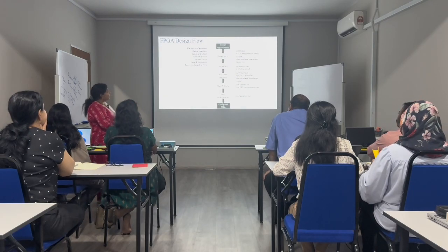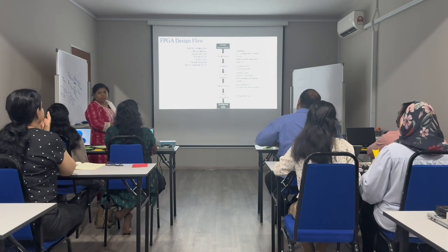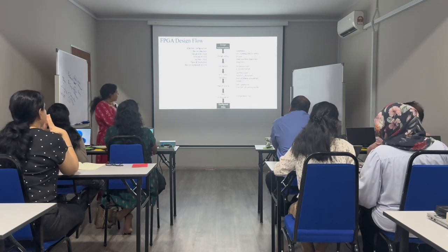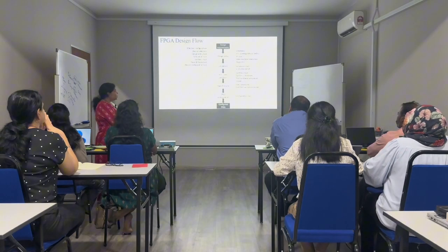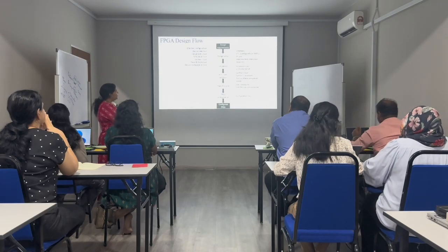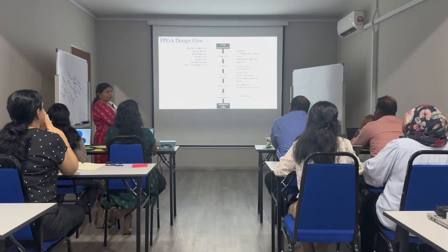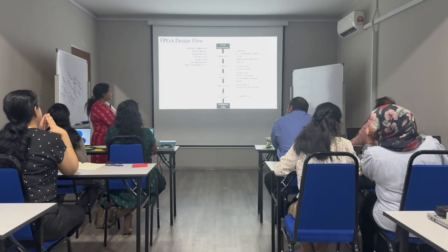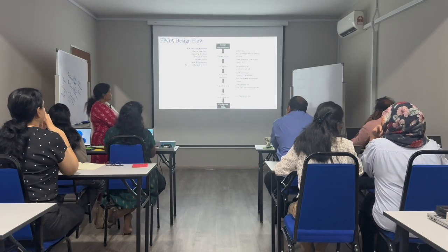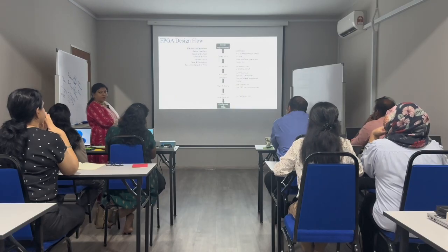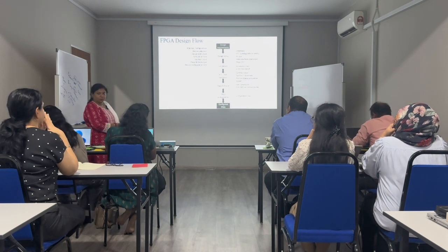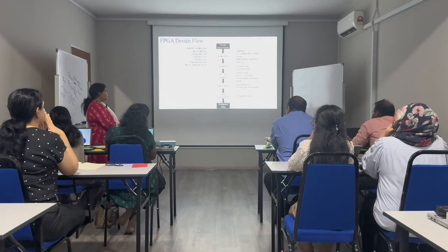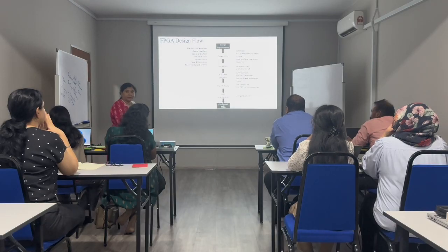After converting into this, we need to check whether the functionality meets, whether the desired output is obtained. That part we will call simulation. Once simulation is done, we need to convert. Until then, this is software. We really need to convert those codes into hardware. The process is called synthesis. In the synthesis process, we will convert the software into hardware, and we saw place and route, interconnectivity, everything will be done. Once this is completed, we will convert the bit file into the system.